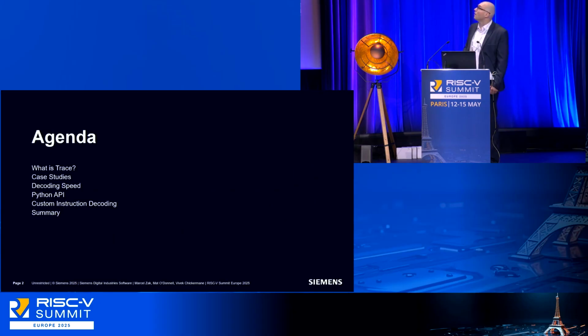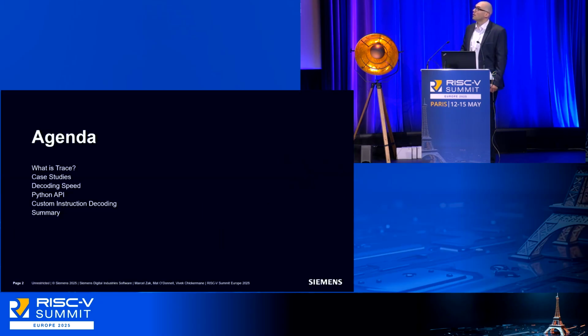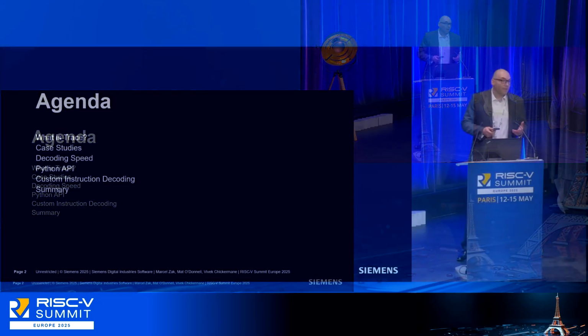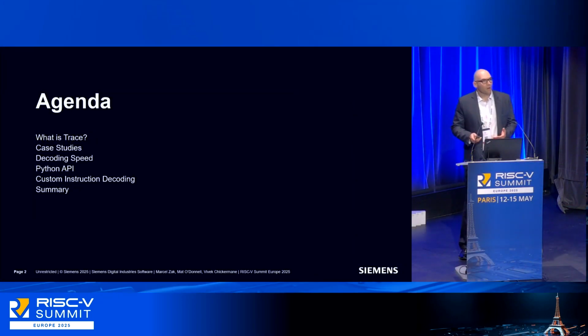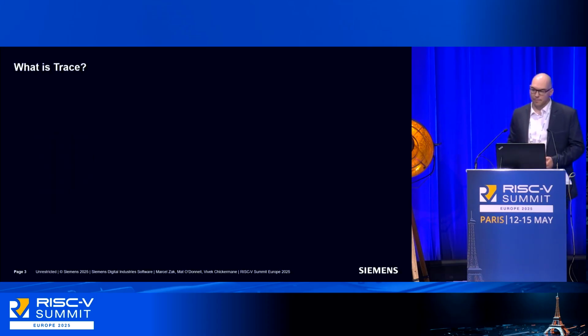Today, I'm going to speak about unleashing the power of RISC-V E-Trace with a highly efficient software decoder. First, I will tell you about what trace actually is. Then I will speak about why you would use trace, what the use cases are. And then I will show you some results and the API of our decoder implementation. I'll also mention how we approach the challenge of tracing any custom instruction. And at the end, I will wrap up with a summary.